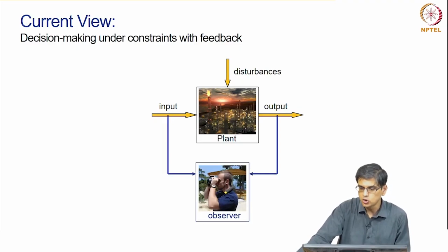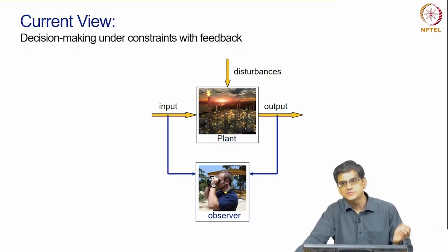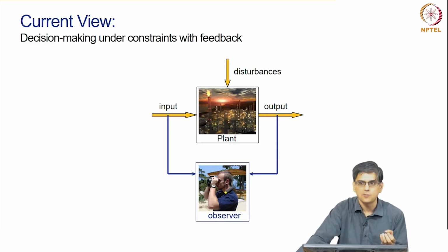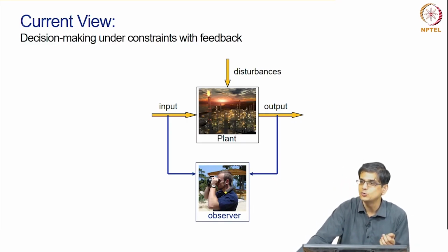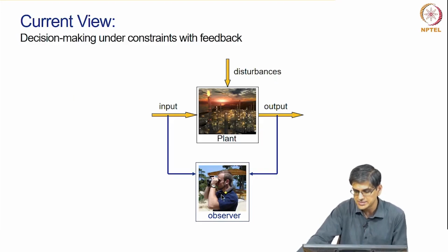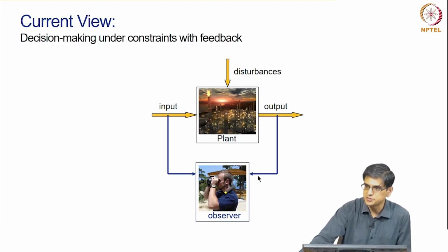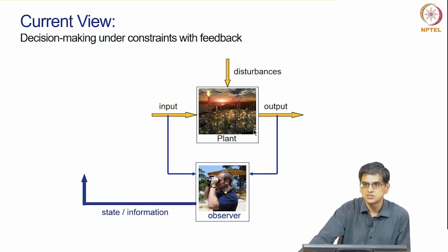Okay. So, you may not always be able to measure what you want to control. For example, you want to control composition from a distillation column, but you can only measure temperature and pressure. So, you infer the composition from the temperature and pressure measurements. The technical term for doing this is an observer. An observer takes the measurements, uses the model, and based on the model it computes the information state of the system.